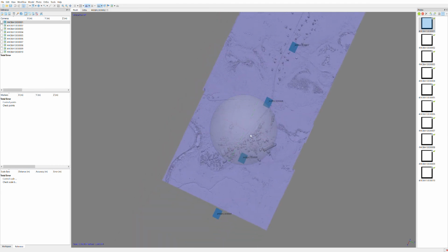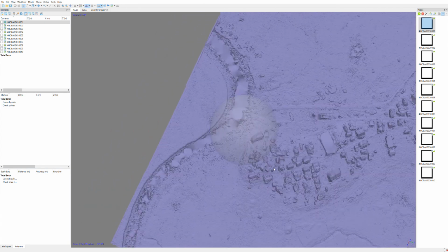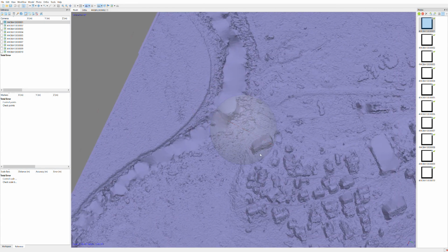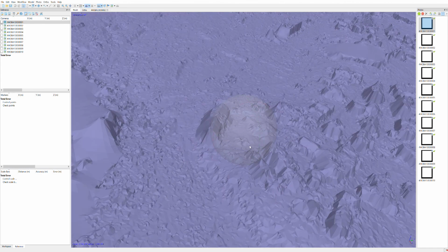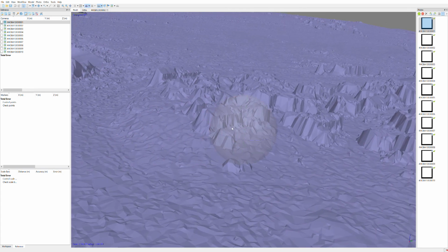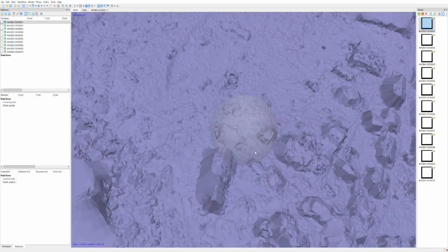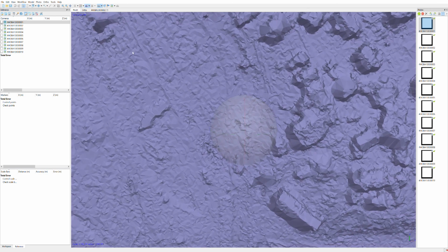If you just looked at one image, they might look further or closer to, like, this riverbank, for example, than they actually are. So the ortho is going to fix that in our top-down image, and the way it does that is by modeling this hillside. Even though it's a little chunky and strange looking, it's still a hillside. It's got the steepness probably about right, so it should be better than just looking at a raw image.